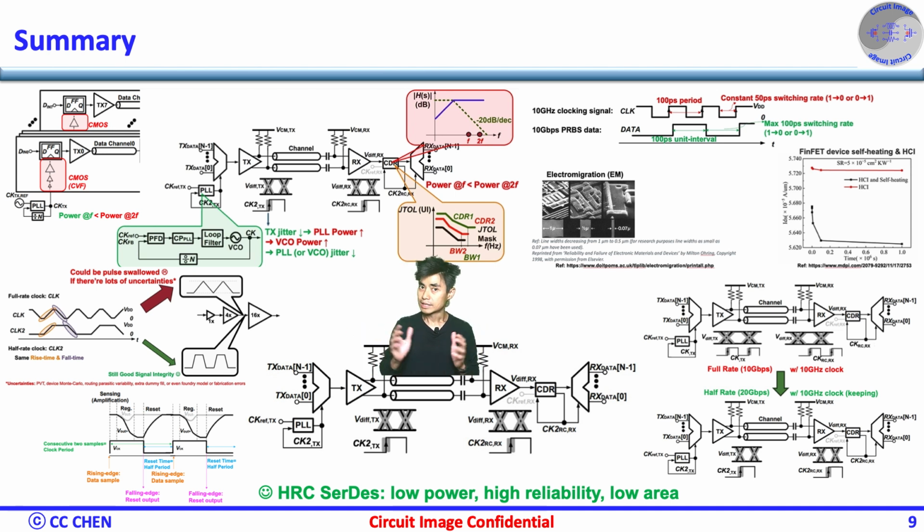Going down to the sensitivity, the half-rate sampling may provide a better timing for CDR or DFE in the RX. Of course, if you would like to make sure your design is compatible with the legacy SerDes or the upgraded one, the half-rate is a good option to help you keep all the benefits without spending time to redesign a higher clock rate, with schedule and design risk.